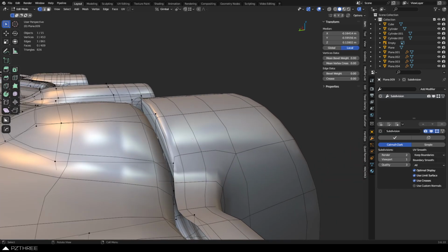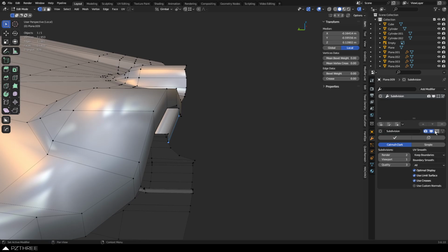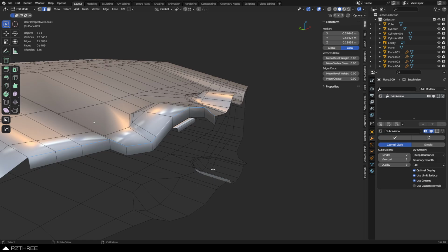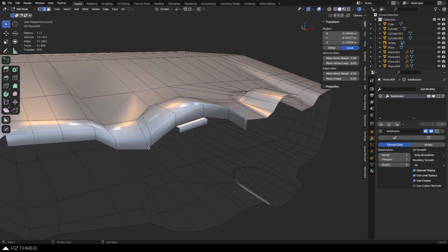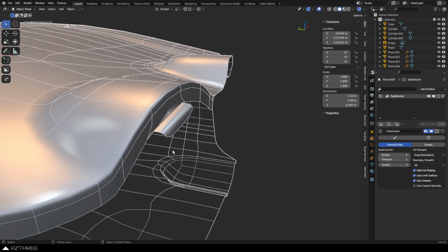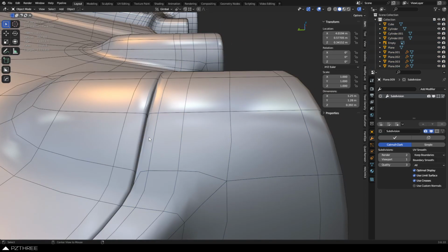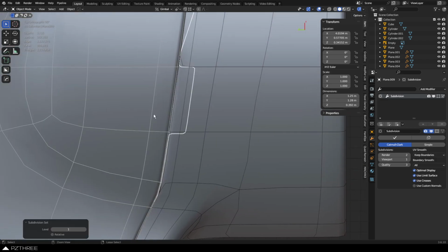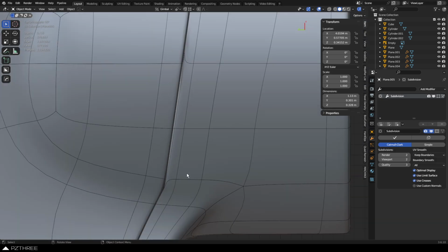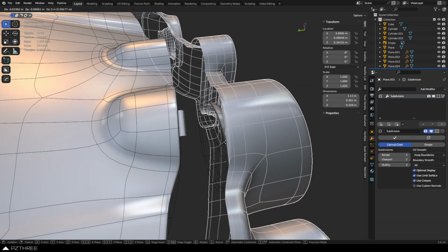With this interior section here, turn subdivision off in edit mode. Probably get away with selecting something like this as well. If you had it selected all the way through, you could probably bevel it, right? So there's always a possibility of doing that as well. And then that's going to give you a really clean bevel up here, basically, that you just simply won't get from that solidify modifier. And it looks cool if you're doing breakdowns as well.